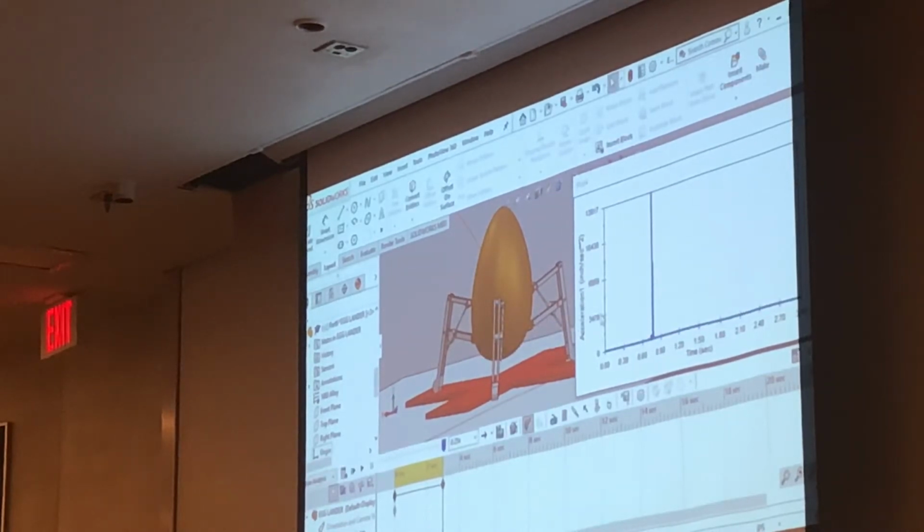But in your plot, if you have a large spike, that's an indication that the egg hit the ground, and that's exactly what you want to avoid. So in a good suspension, you should have something that's not a sudden spike, but more like a smoother hump. And your value should be in the neighborhood of 1 to 2,000 inches per second squared, rather than about 14,000. Okay?